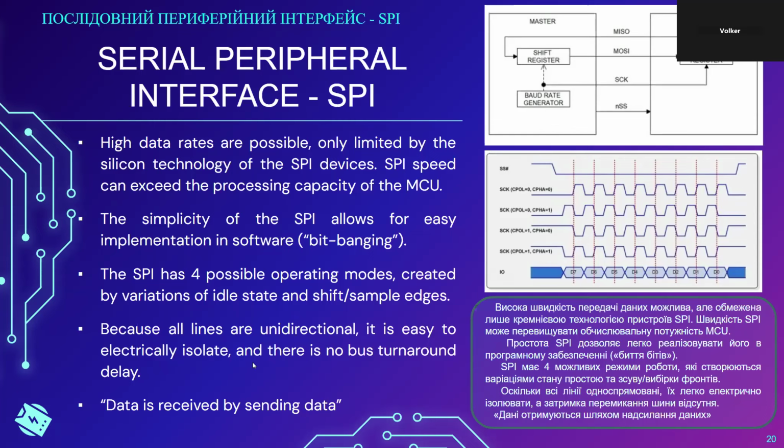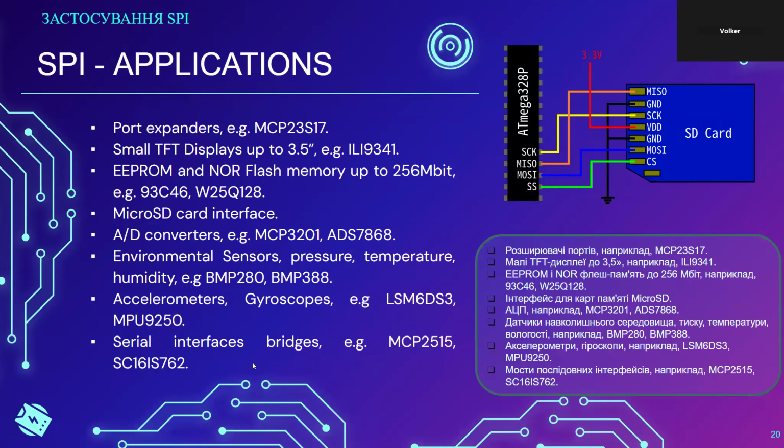Applications for SPI. Port expanders. For example, if you don't have enough output pins on the microcontroller that you have chosen, there are specific devices that can be connected through SPI and that allow you to connect more GPIO pins to your microcontroller. One of them is the MCP23S17.